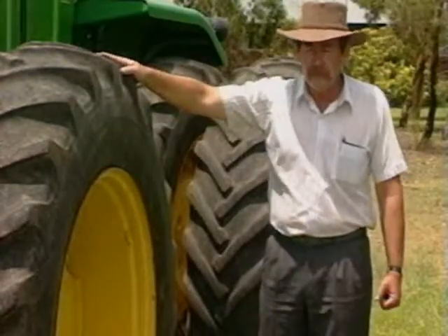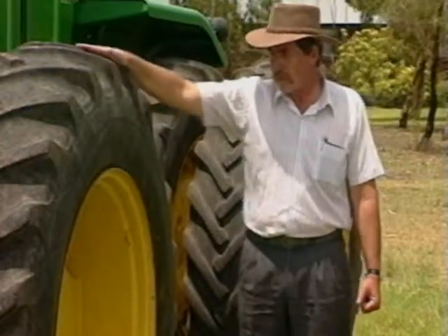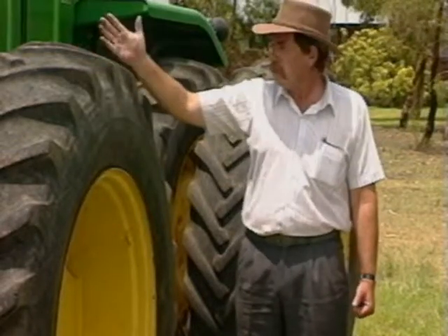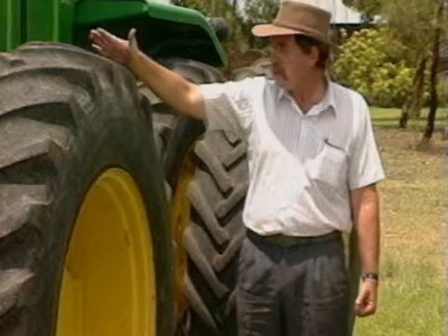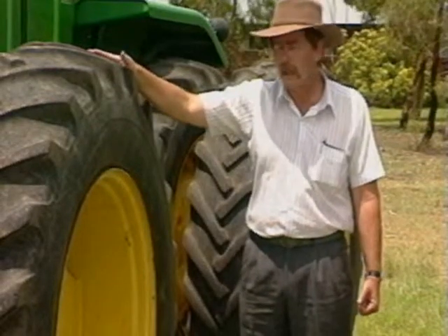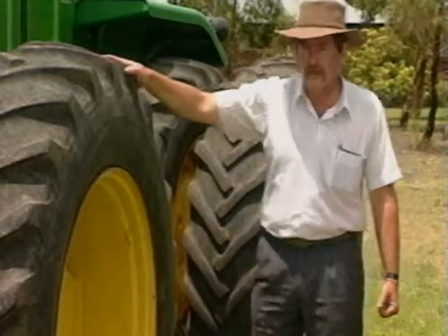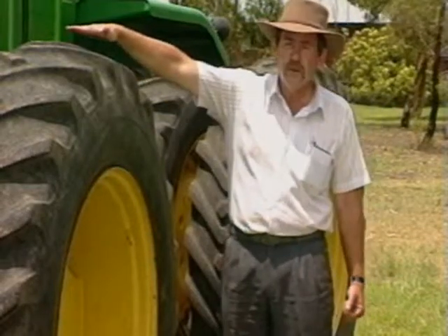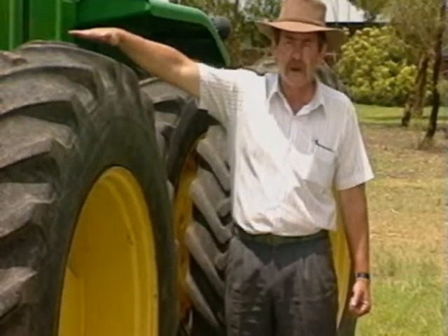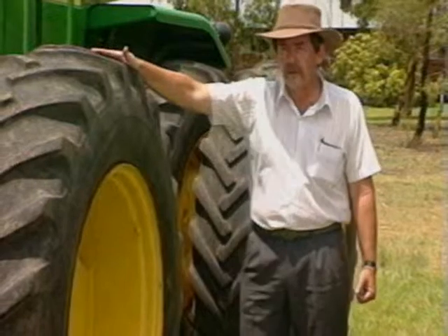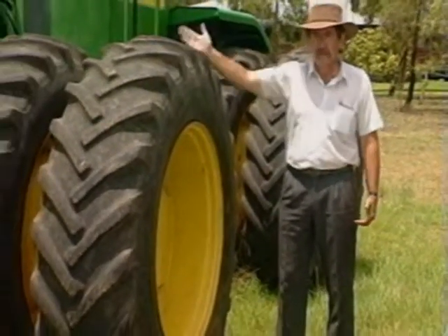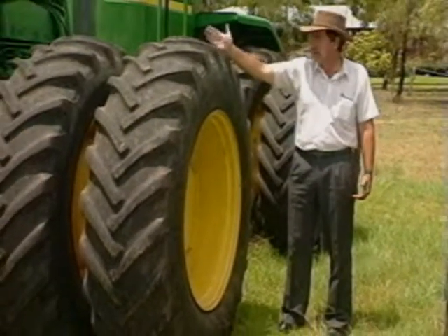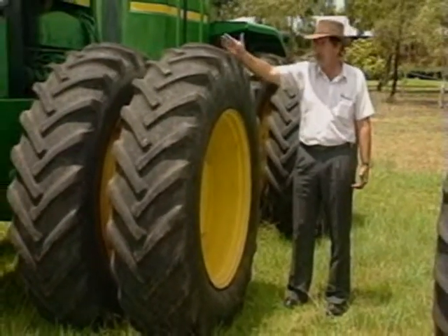Finally, tyre life. When we look at tyre life, farmers are often concerned when they put new tyres on their tractors, and within the first 50 hours it appears that the tyre is worn very, very quickly. This in a lot of cases is quite true, because when one considers a new tyre, the lug is very high, and when the tyre rolls through the ground, generating traction, the lug tends to move. And that's what causes tyre wear. As the lug moves backwards and forwards, the tyre wears.